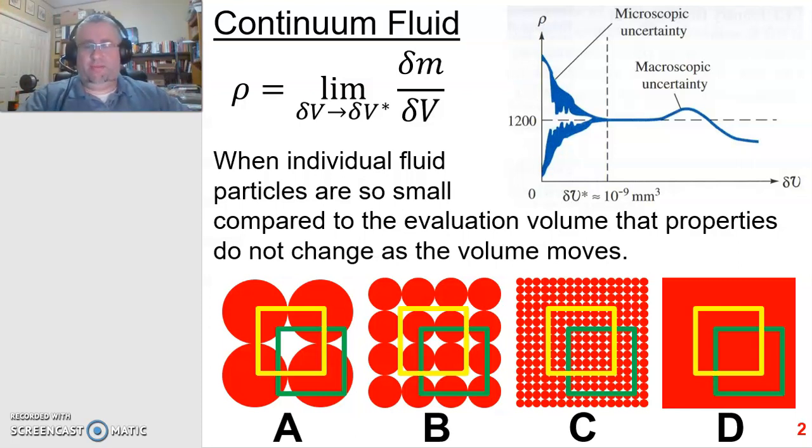Places where the continuum fluid assumption breaks down are situations where you either get really, really small, or you have fluid that is incredibly diffuse, so has really, really low density. For our purposes, none of the oils or waters or gases that we're going to deal with violate those conditions. That's good, because all of the tools that you learned in your undergraduate fluid mechanics class, for the most part, assume that you're dealing with a continuum fluid, like water at room temperature or pressure, or air at standard temperature and pressure, for example. Those are both continuum fluids.